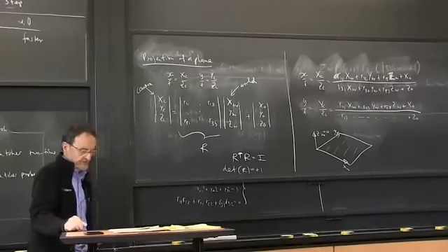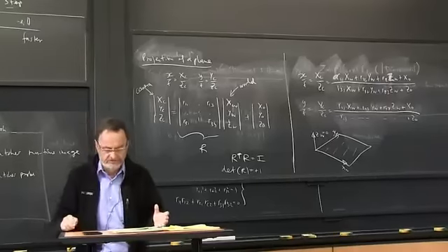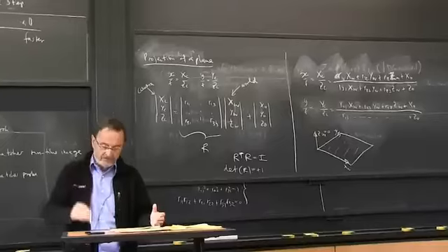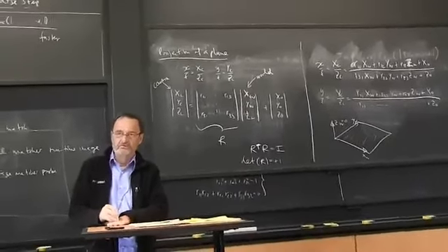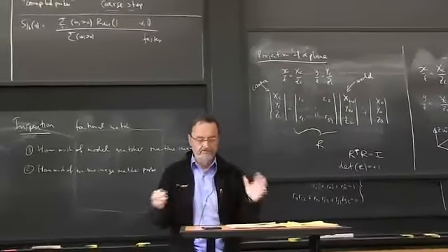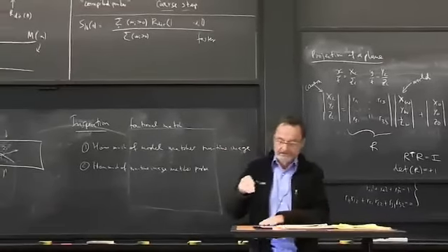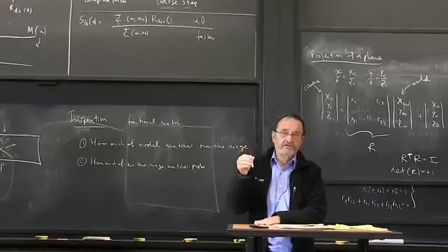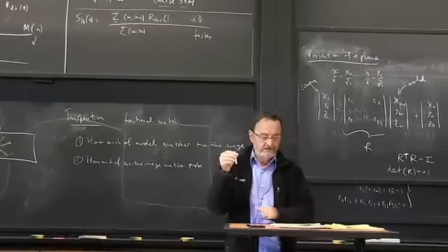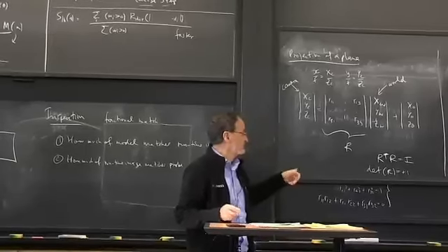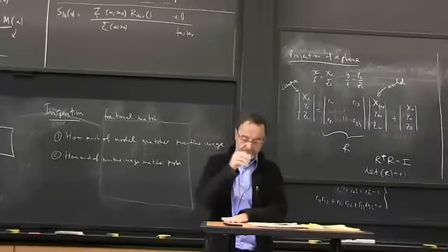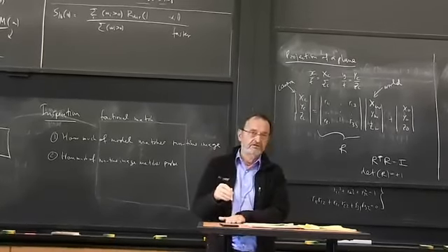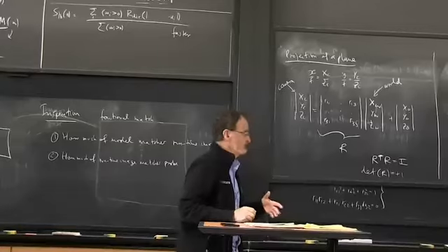And so it comes up in industrial machine vision in many ways. One is, obviously you want to try to get your optical axis as perpendicular as possible to the surface you're interested in, whether it's a conveyor belt or the surface of the road or whatever. But there inevitably will be some small error, and inevitably someone's going to bump into it and change it slightly. And this takes care of it, because this slight generalization allows you to deal with other camera orientations. You don't have to have a perfect orthographic projection. You can have a slightly skew one.